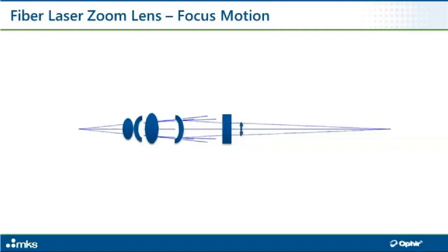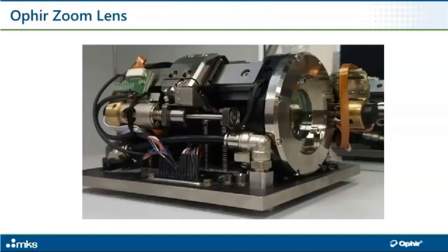And actually, we designed such a lens. You can see the lens we designed and manufactured here in this picture. Here you can see the water cooling channel. The water cooling is required if you want to operate the lens for high power lasers of 6 kilowatts and above.